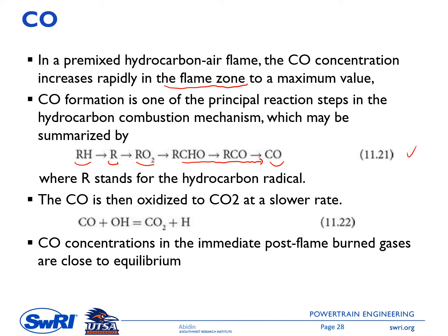The CO is then oxidized to CO2 at a slower rate, following equation 11.22. CO reacts with OH to produce CO2 and a single H. CO concentration in the immediate post-flame burned gases is close to equilibrium.